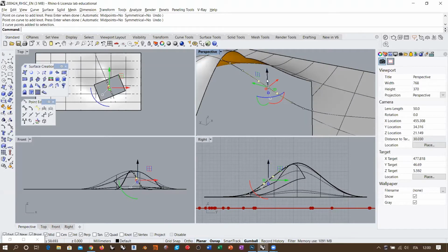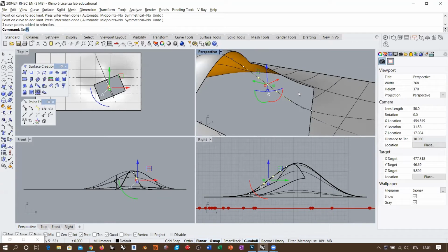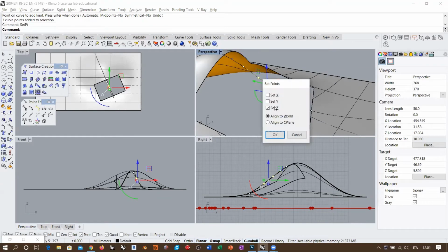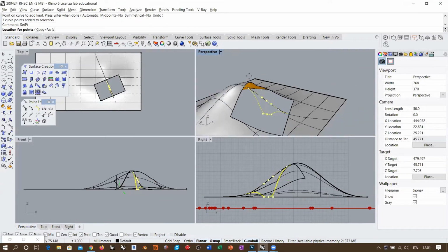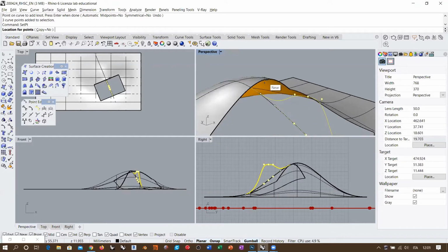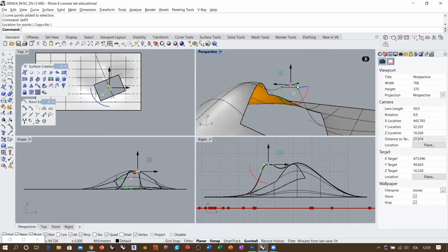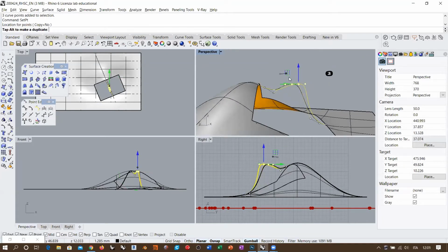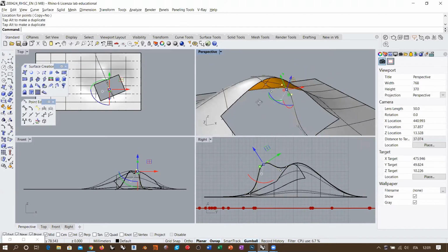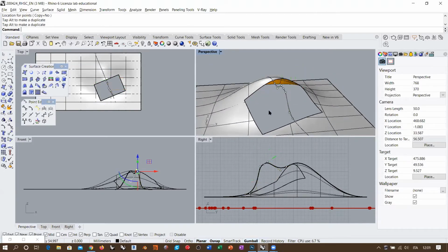So for example, I can take these 3 points, set the z value to a value like, for example, this point here. So I am telling this curve to reach this particular height, okay? And I can create this kind of controlled deformation for this curve that will correspond to eventually the surface that will use this curve as an internal guide, okay?